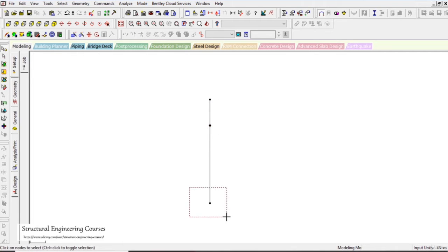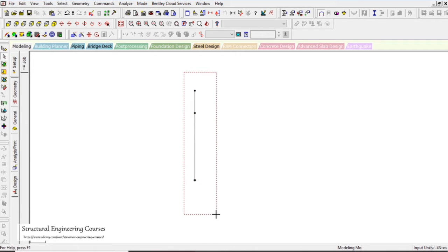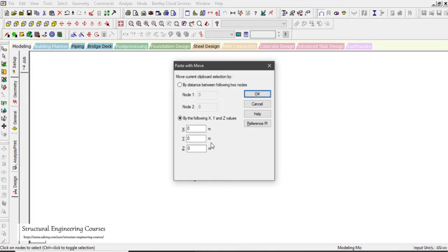After that, basically this is the mass tower that we are talking about. In this example, to consider things simply, and also to make this lecture simple, I am just assuming it to be a simple cylindrical pipe here, like a pole tower. So after that I want to support this 16 meter height pole tower with the help of the guy wires. So what we can do is just copy this joint here, and then we can enter